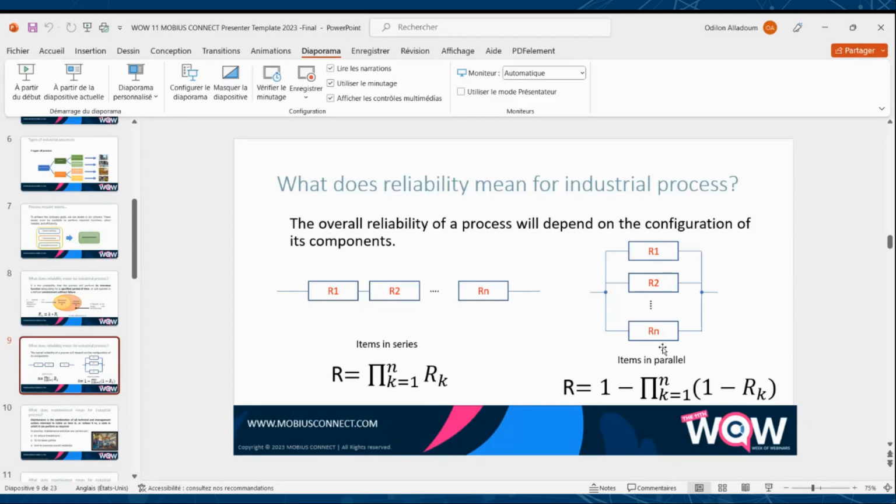The way to obtain system reliability in such cases is to break the total system configuration down into homogeneous subsystems, then consider each of these subsystems separately as a unit and calculate the reliability. In summary, if we want to analyze the reliability of an industrial process, first we must know the system, how the system is configured, and we also have to describe the system and draw the block diagram.